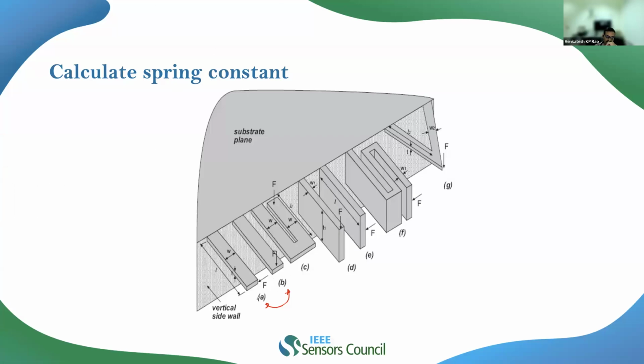If you look at this carefully, if you take your scale, you can apply a load from the top and easily bend it. On the other hand, if you apply it from the side, you can't bend it so easily. Why is it so? Because the sectional inertia from the side will be quite large in comparison to that from the top. In this figure, you can see that the thickness is quite small in comparison to the width. Since the width is larger than the thickness, WT cube divided by 12 is of course much less than TW cube divided by 12, right?